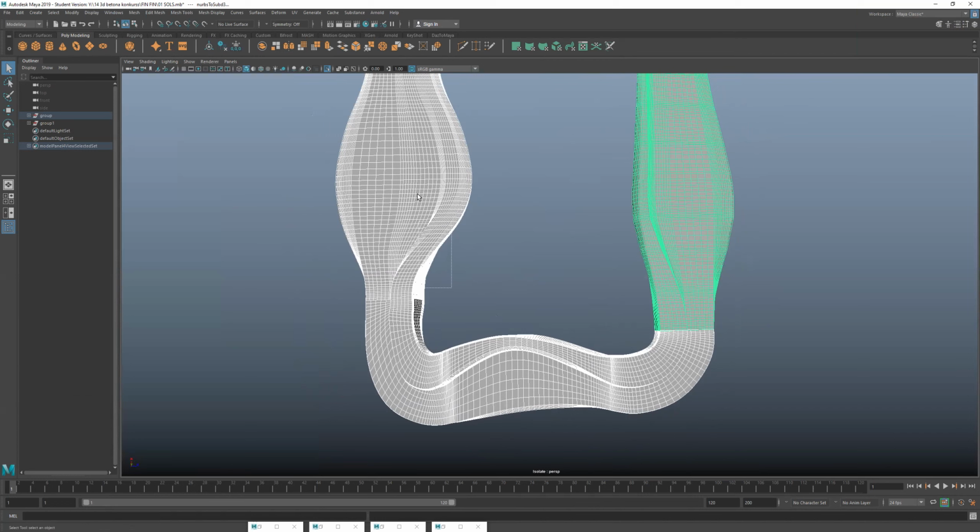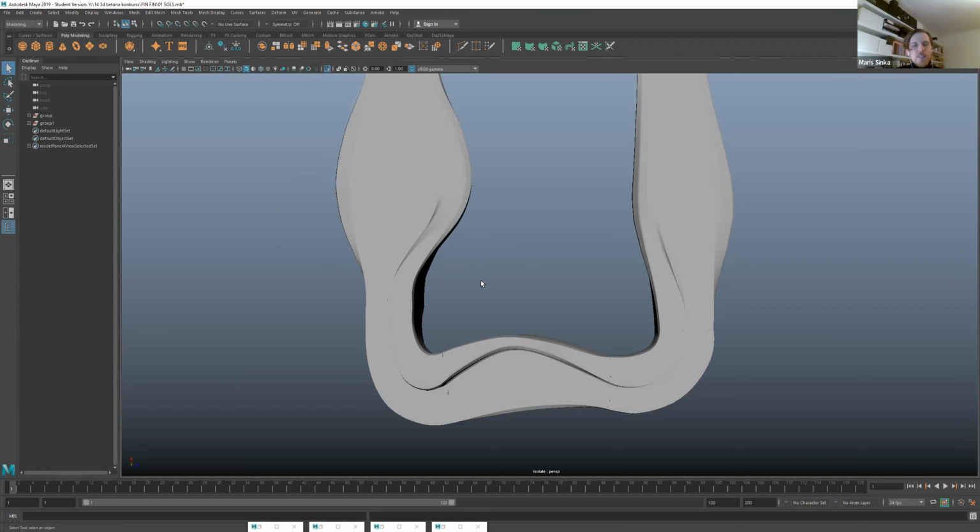Well, you must understand that those 20 degrees were not on purpose, that you will take 20 degrees and make the maximum height of the object that has 20 degrees. You can of course stick with the 20 degrees, but it's not that the printer has been tested for every object, and at 20 degrees every object can be printed. So less angle is better for me. More angle is better for your creativity, like how the object looks. So yeah, if it's possible, get it lower. If it's not, then you will leave it, and we will need to think about it afterwards.